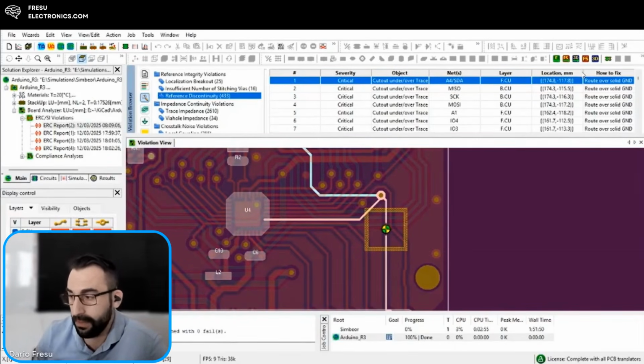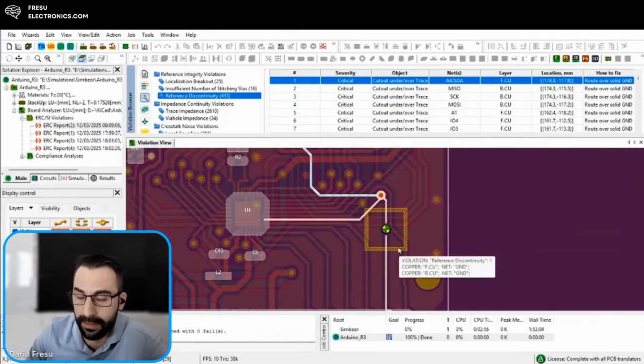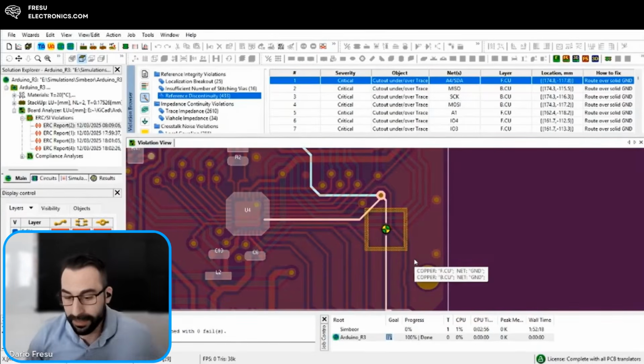Because we saw, if I use the stackup in here, so if I use 2 signal layers without the return reference planes, trying to establish in here coplanar waveguide, which are not coplanar waveguide, then what can I choose? Because if I try to use this board, I have no chances of passing EMC test. So I can choose a 4-layer design. Now, the problem when there's in projects that tells you, oh, you need to choose the cheapest possible board, your answer should already assume that it's a 4-layer.